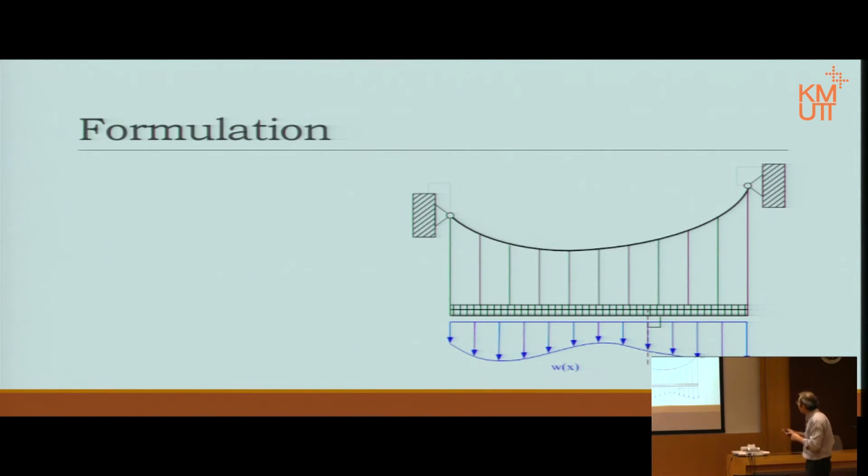Now the main cable is the one that we look at in the middle span, and then of course we have the suspenders, or the vertical cables. Then the slab, or maybe the beam, depending on the system of looking, but usually it's the beam, hangs onto the cable.